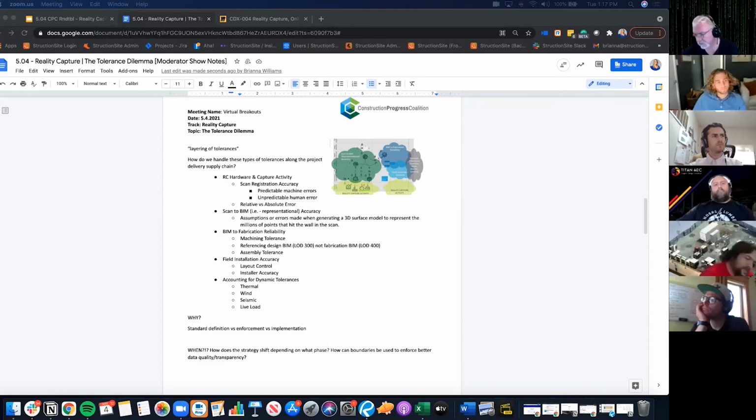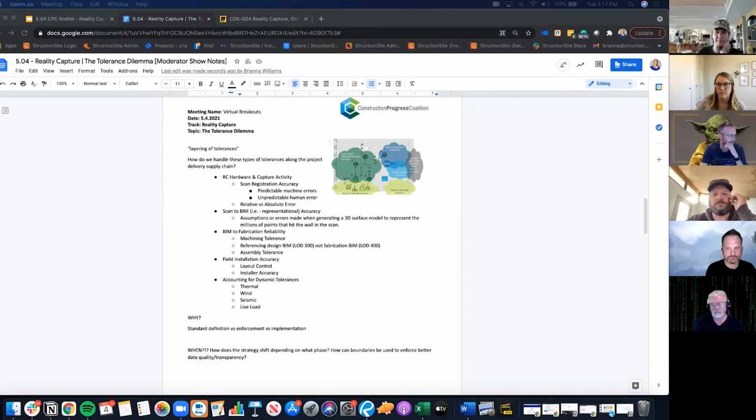So I was going to chime in earlier, but we've actually set several systems within rooms where we did demo. We scanned before the demo, we scanned after the demo. We then went in and set control points with trackers. We mocked up the entire system, prefabbed it, took it into the room and made 37 welds in the room, and only had to cut pipe in 3 places, in X, Y, and Z. And that was it. That was about 350 feet worth of pipe, all in different angles and corners, mocked up from a model.